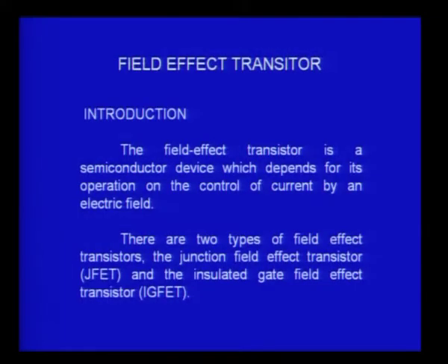These are the variations of the IGFET, insulated gate FET, and they are the ones which basically revolutionized the field of electronics, because these field effect transistors and the metal oxide semiconductor transistors can be fabricated on planar technology, on one single plane of a semiconductor silicon wafer, and therefore you can put more density of those active devices per square inch, and that brought in the revolution that you see all around in electronics, basically in integrated circuit electronics. So JFET and field effect transistor in general is a very important step in the development of electronics.